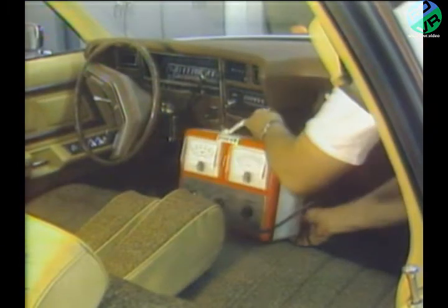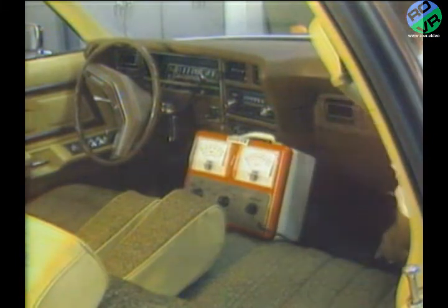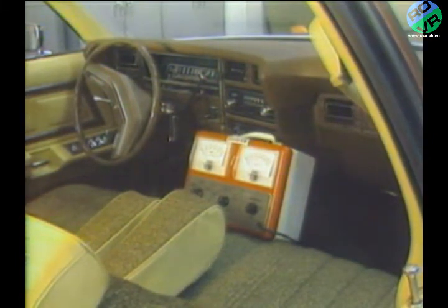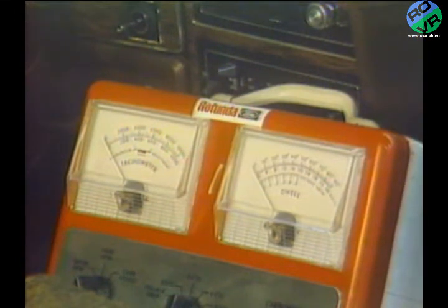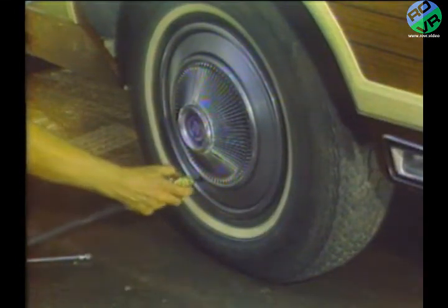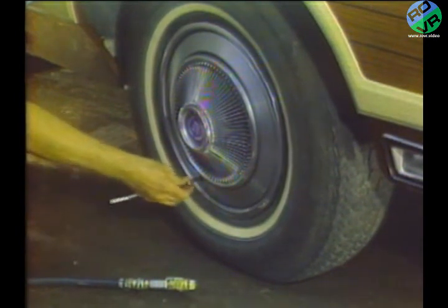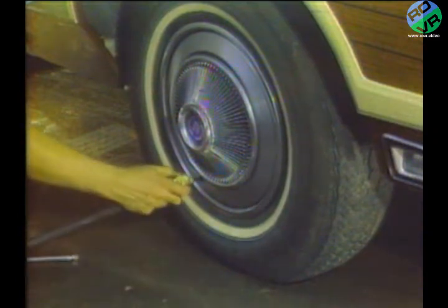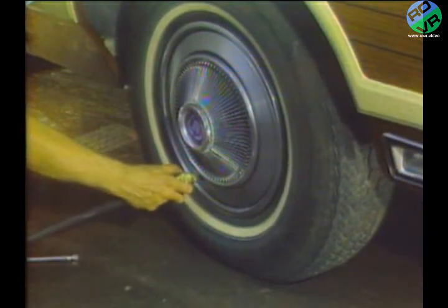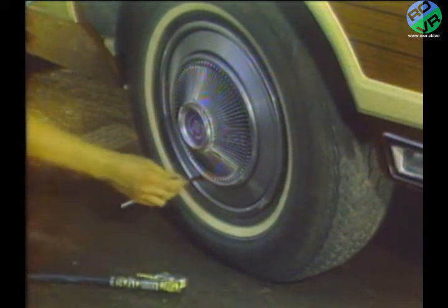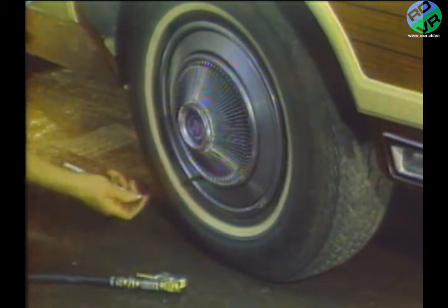There are general road testing procedures that apply to all NVH complaints. For example, prior to any road test, always connect a tachometer. It's important to know at which engine speed and road speed the NVH problem occurs. Some technicians set the correct tire pressure before every road test. However, other NVH technicians prefer to road test the vehicle with the same tire pressure as the owner used. Either method is acceptable as long as you follow the same procedure before every road test.